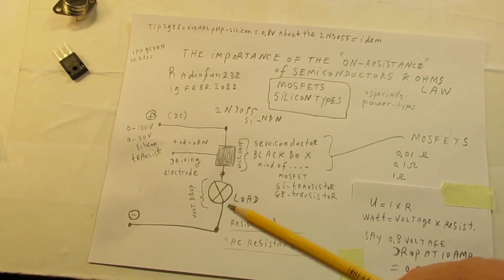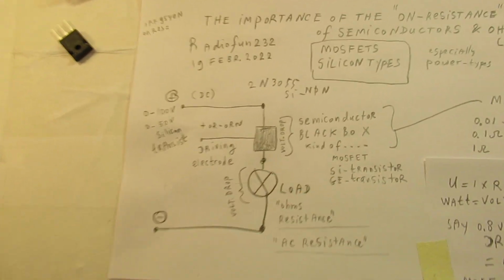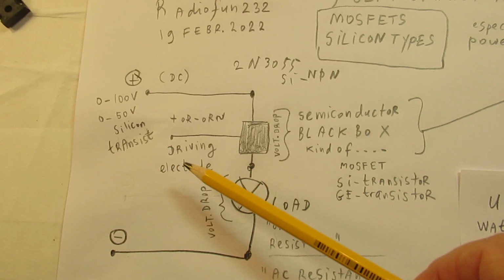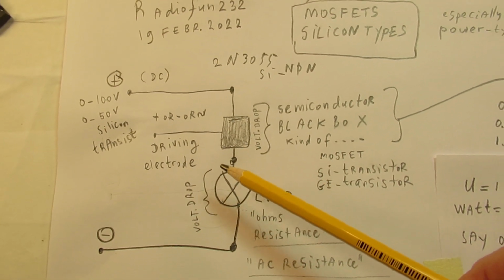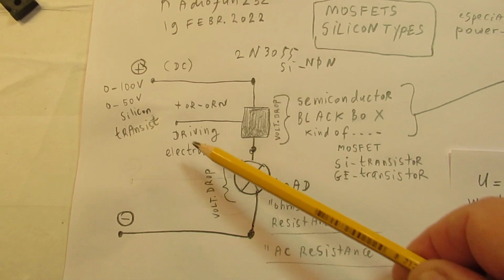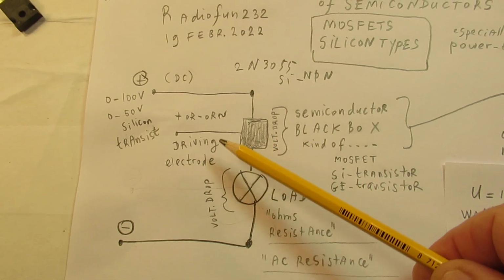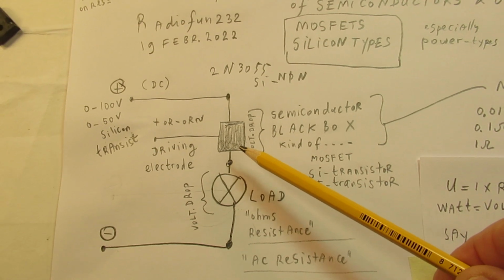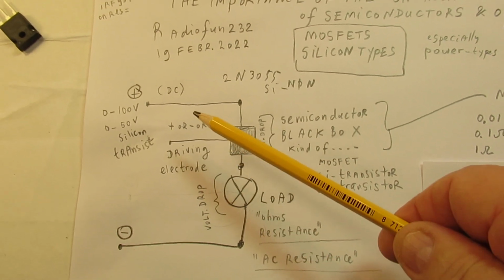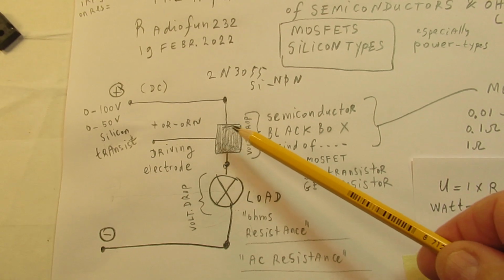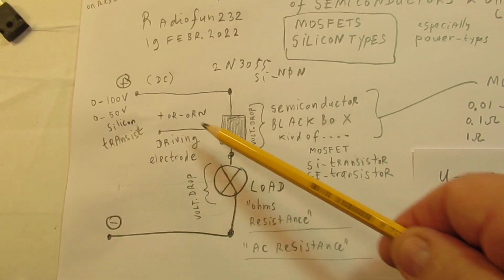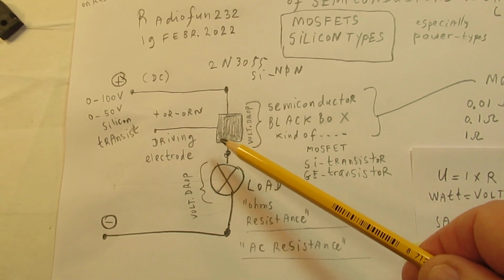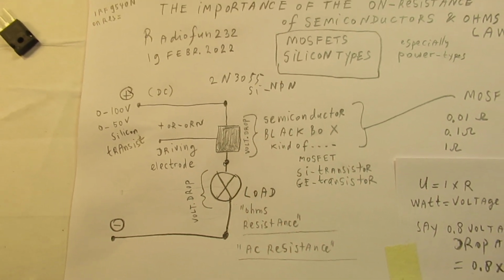I'm not talking about a situation where an NPN transistor or a PNP transistor is driven by pulses. Only this is a situation where we have a kind of static charge, static current charge in case of MOSFETs, and current in case of bipolar transistors that will drive the transistor, MOSFET or whatever, into saturation.